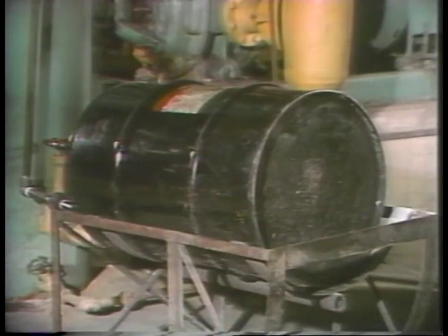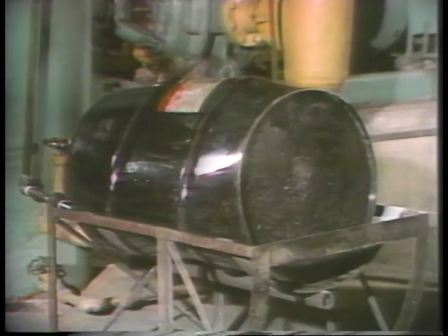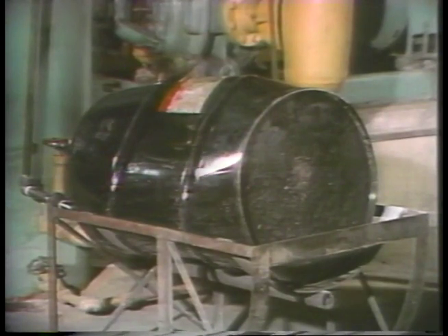Even though the drum construction is quite sturdy, you can see the great amount of force applied as a result of the differential pressure between the lower pressure inside and the higher pressure outside the drum. It's a good idea to always make sure vent valves are open when you drain or fill tanks. In this segment, we've talked about the conditions resulting from the compression and expansion of gases, and we've seen how Boyle's law relates to plant operation.